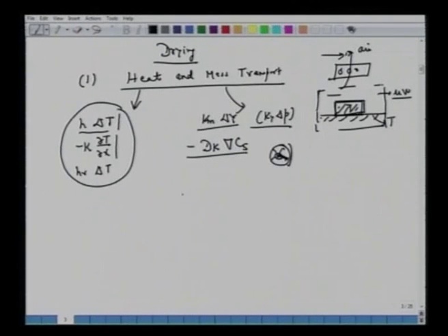Of course both of them will have an independent effect, but in some cases you can see that heat can improve the Knudsen diffusivity, so there is a simultaneous effect also. We can have unsteady state problems, a function of time. If you start with a solid which is cold, at room temperature, and now you bring it to a very high temperature, it will take some while before the temperature of the solid becomes the same as the temperature of your heat plate. So it's a function of time. We can have an unsteady state problem, or we can have a steady state problem.